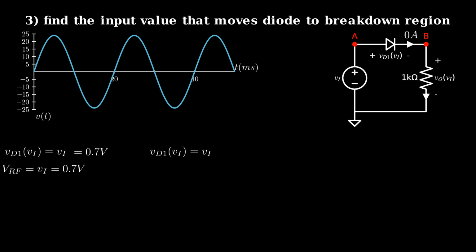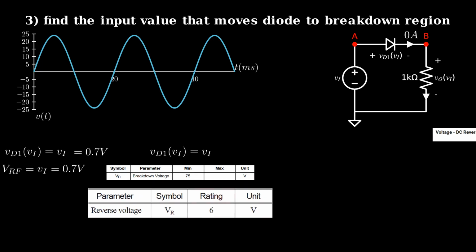For this, we need to know the breakdown voltage. This value will vary with different diode models. What won't vary is that the value is specified as a positive value, even though it should be a negative value. If we are keeping the diode VI plot shape in our minds, this breakdown voltage is in the left-hand plane. The specified breakdown voltage is the magnitude of the reverse voltage. If you keep your signs consistent as I have, it'll be negative.